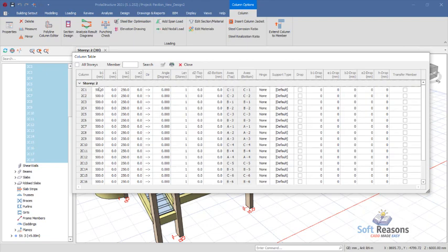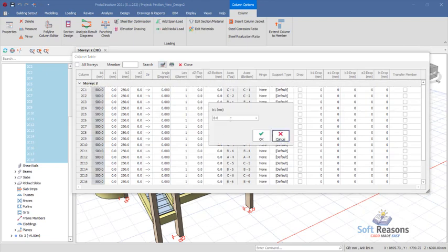So in the column property, we have our sections to be 500 right there. Change these sections to 450 right there. You can maintain the width to be 250, okay, but we need to change this to 450, and then you type 450 right there, 450, just like this. Click on the OK option.